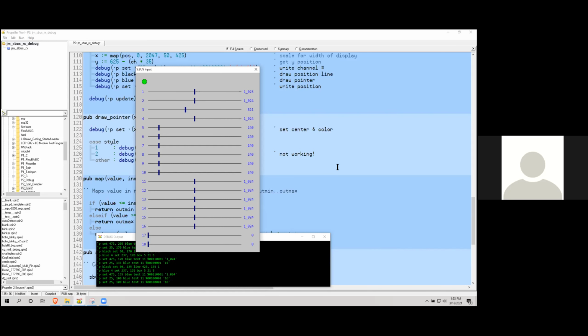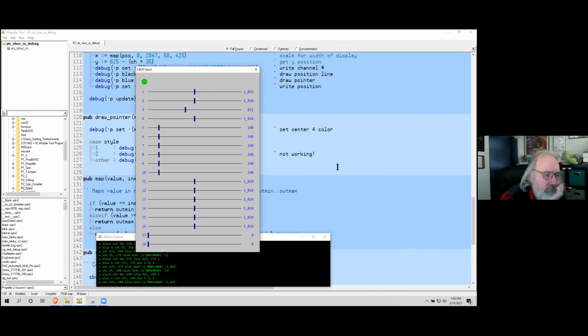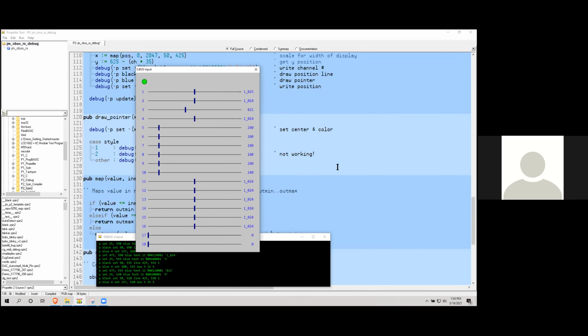Now the Skyfly, they have their own protocol. sbus is a little interesting in that it's an inverted signal. So the idle point of the line is low, and then it goes high for a start bit, and all the bits are inverted. It also uses a 9-bit value. So there's 8 data bits plus a parity. And then there's 2 stop bits, which is not a problem.